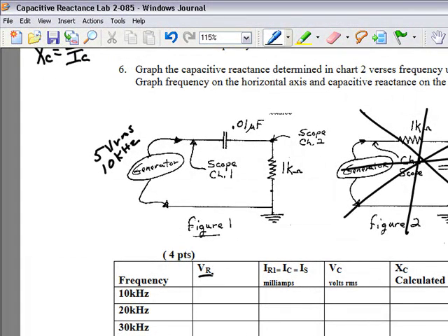First thing we want to know is voltage across the resistor. So all you have to do is take channel 1 and place it directly across the resistor. Measure that voltage. Typical voltage you might measure is maybe 2.72 volts. Now why we need that measurement is to find current, because we can find current flowing through the resistor by taking voltage across the resistor divided by the resistance.